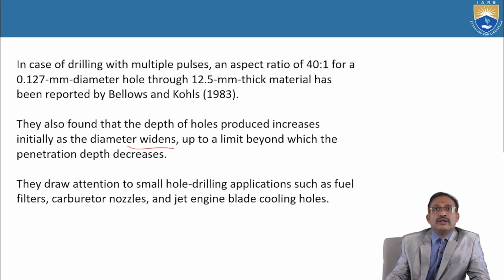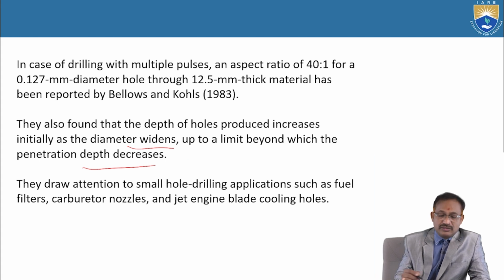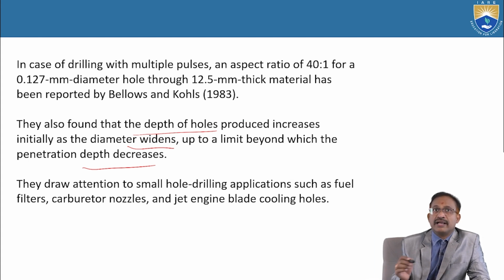The depth of holes produced increases initially as the diameter widens, up to a limit beyond which the penetration depth decreases. After a certain limit, it starts decreasing. The depth of the hole initially increases along with the diameter of the hole, but later on it will be decreasing.